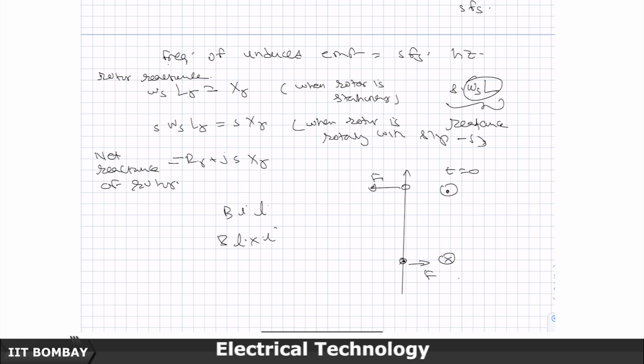So the point is, because this is rotating at omega in this direction, this whole thing will be trying to keep catching up with it. So it is like a cat and mouse kind of thing. The mouse here is the rotating MMF wave of the stator, and the cat is the rotor, the winding on this.